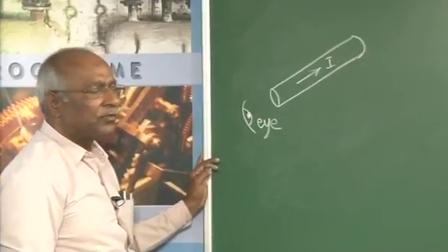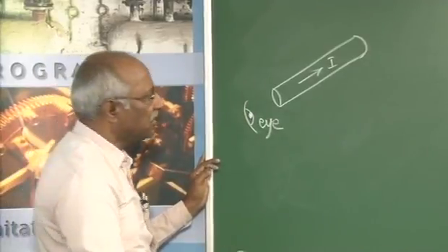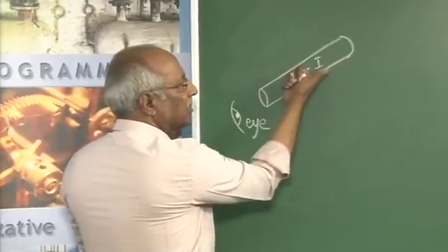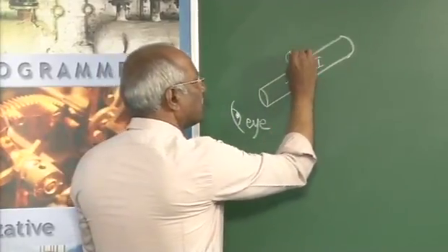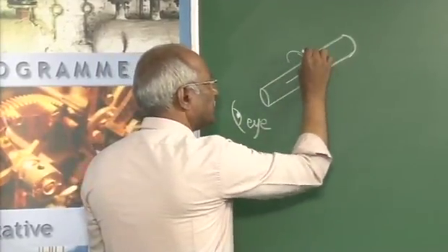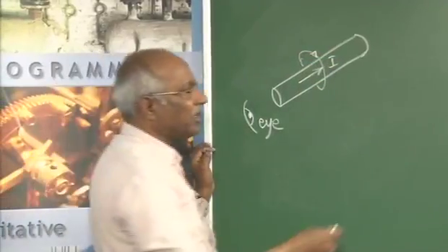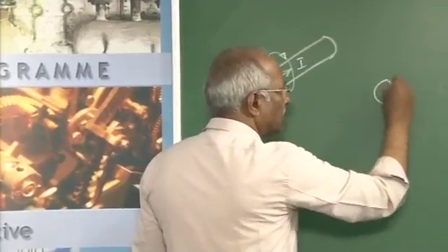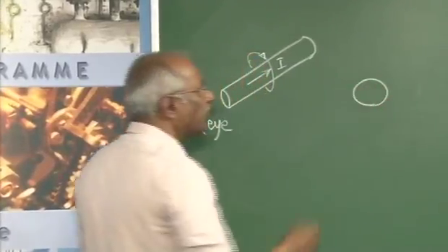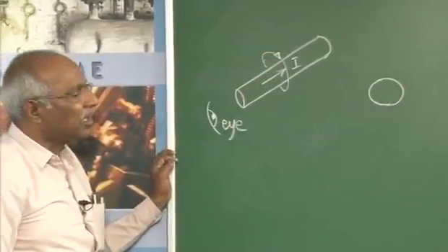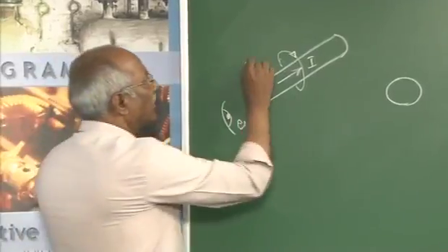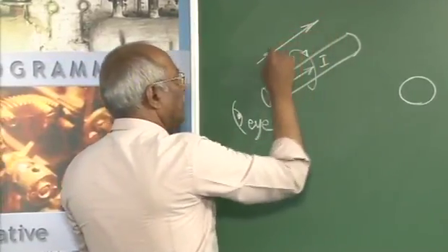What's the direction of the flux produced? As such, it can be seen here now. This is the direction of the current, so therefore the flux produced must be this way. This can be indicated schematically like this. The conductor is represented by a circle. When it comes to the direction of the current, an arrow is considered to be the reference.